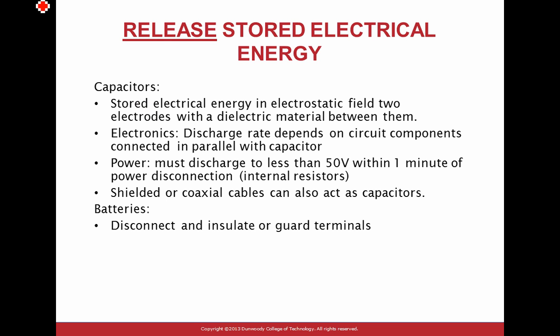Release stored electrical energy. The first and the most important one is capacitors. Capacitors have enough energy to shock people or create fire. Stored electrical energy is stored in an electromagnetic field. So you are to discharge it. The code requires you to bring the voltage below 50 volts in 1 minute.